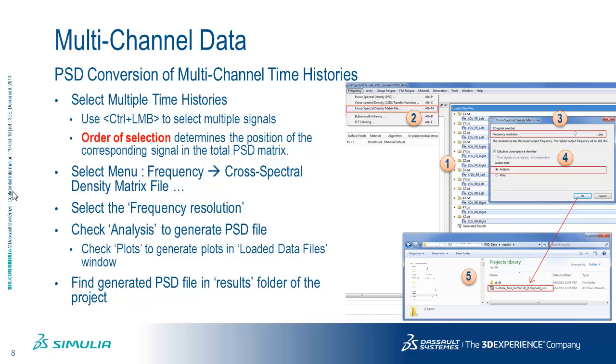Okay? And here, the key point is the order of selection. When you select the time history, you should use the regular Windows multi-selection scheme, like control select.